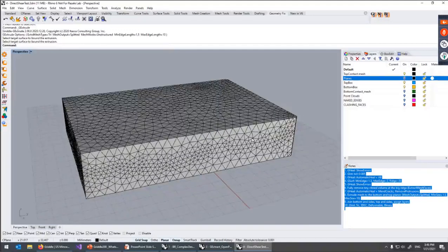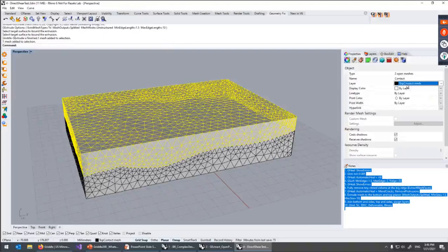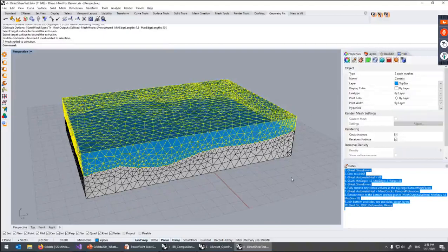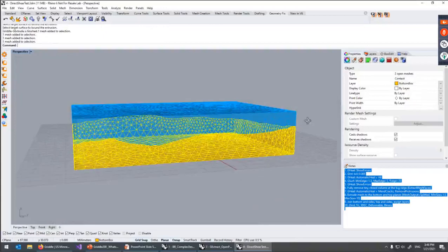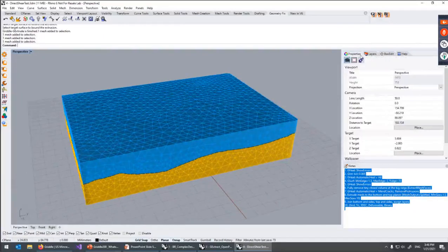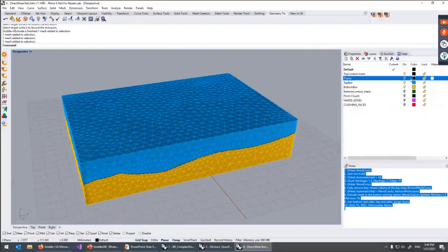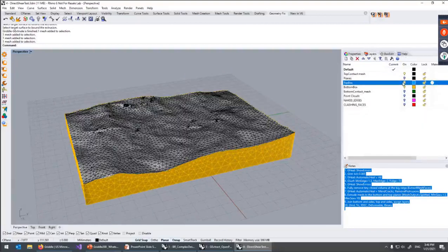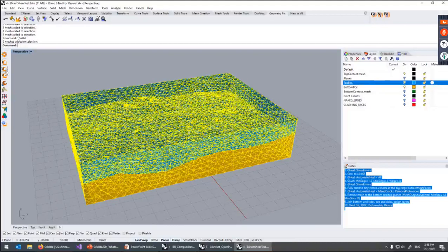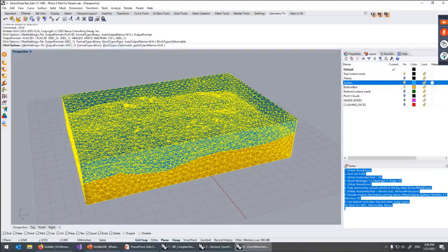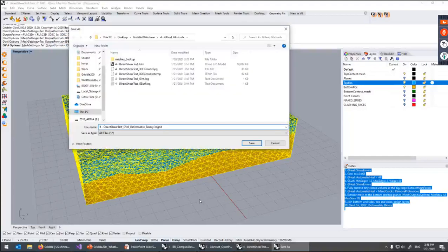Now I can assign these meshes into different layers. Let's say this is going to be our top mesh, top box, and bottom box. So we got full model in less than 5 minutes. And if we hide one of these domains, we can see that in between is our surface. Now we can easily create 3D model by volume meshing. Let's select 3D 7 and deformable formats. So we get only 2 blocks here. And we're gonna save it.